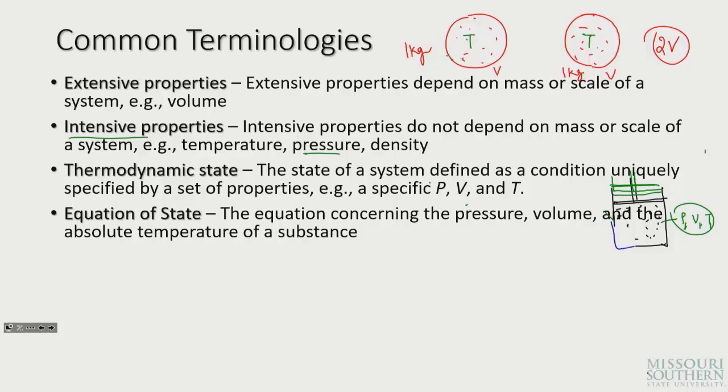Okay, and those variables in general are mechanical variables supplemented by the thermal state of the system. Okay, so for example, the thermodynamic state of a gaseous system can be specified by its pressure, volume and temperature, just like we described. But out of the three variables P, V and T, only two are independent variables, and the third may be considered as their function.